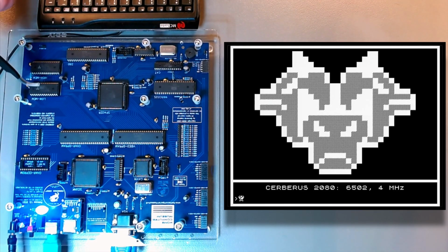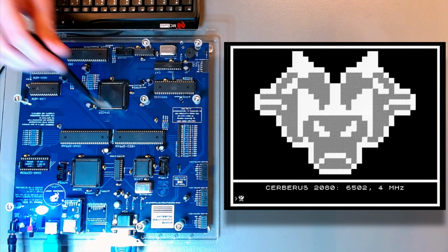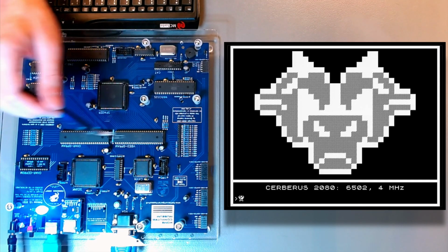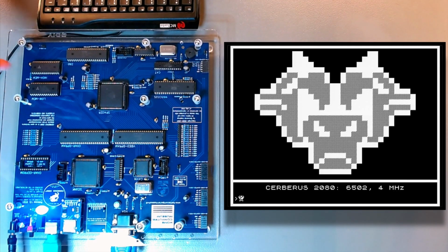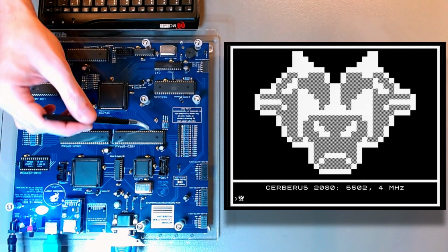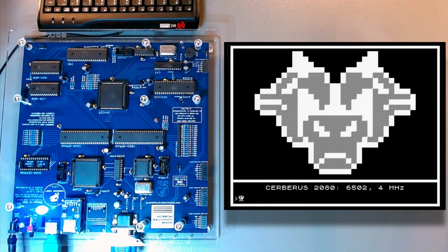And then we have two chips for SRAM, each one 32 kilobytes. Combined, they have 64 kilobytes, 60 kilobytes of which are user accessible. The other 4 are allocated to the video and character memories. So you have actually 64 kilobytes of addressable RAM in this architecture. And there is no ROM. And you might ask, well, how come? Where is the kernel? Where is the BIOS?